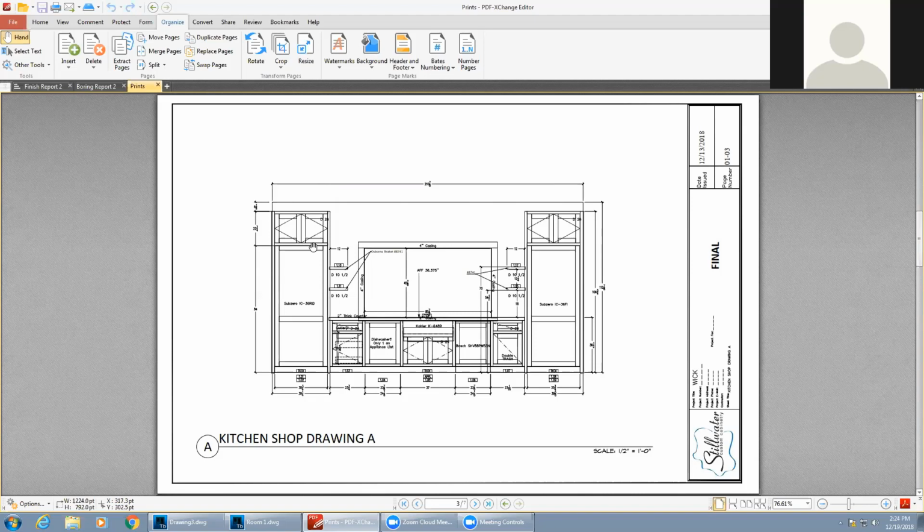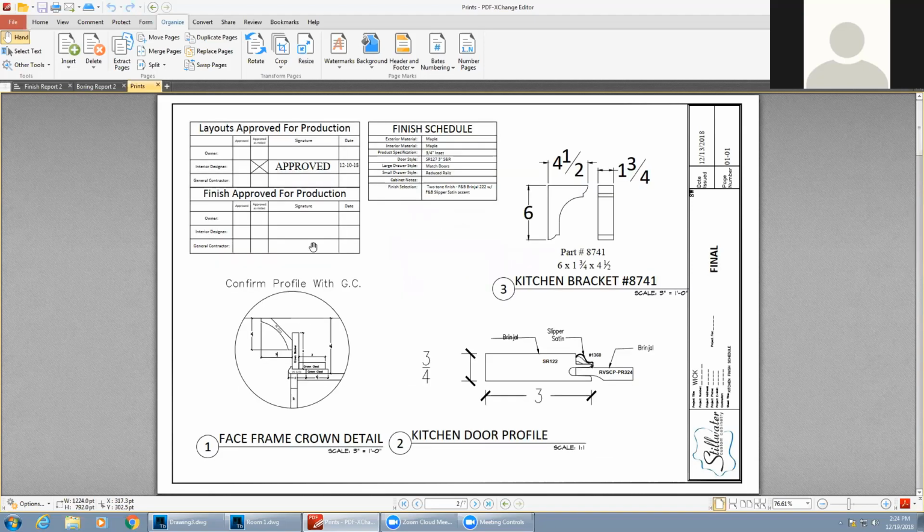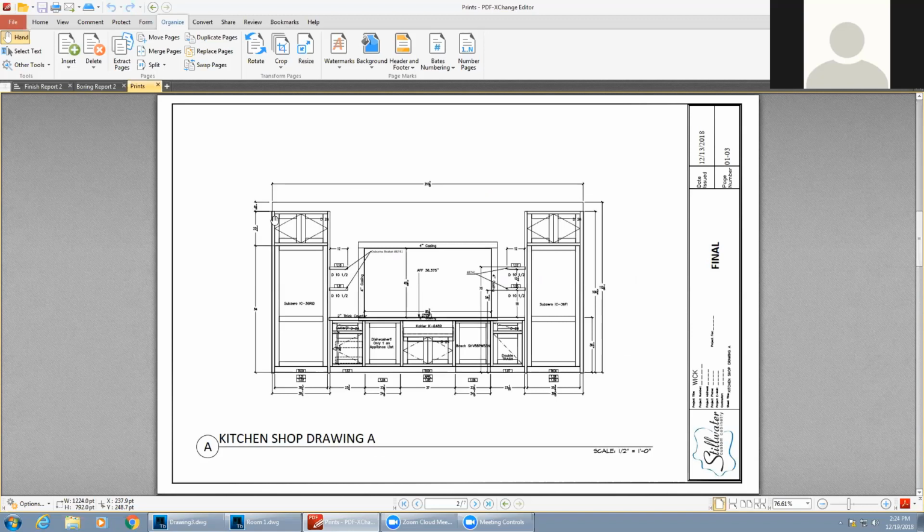The other thing to point out here, and again, I don't know how many people are watching or what type of software they use, if any, but once you draw this Microvellum product in here, all of these other drawings are reading that product. So these 2D elevations automatically adjust. If I was to change this cabinet from 23 1/8, it would automatically adjust the drawings, the dimension lines, all of that would happen automatically, and then I would reprint the drawings.